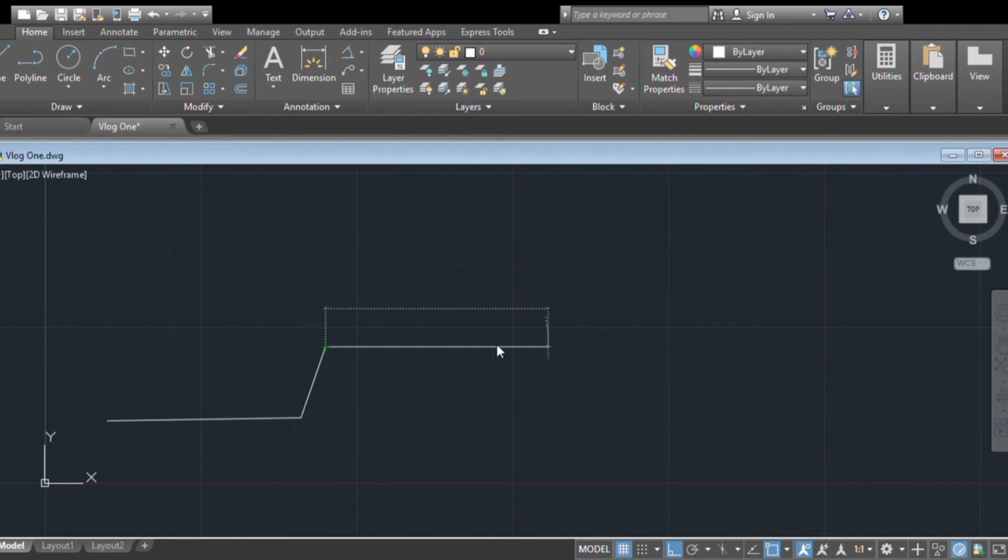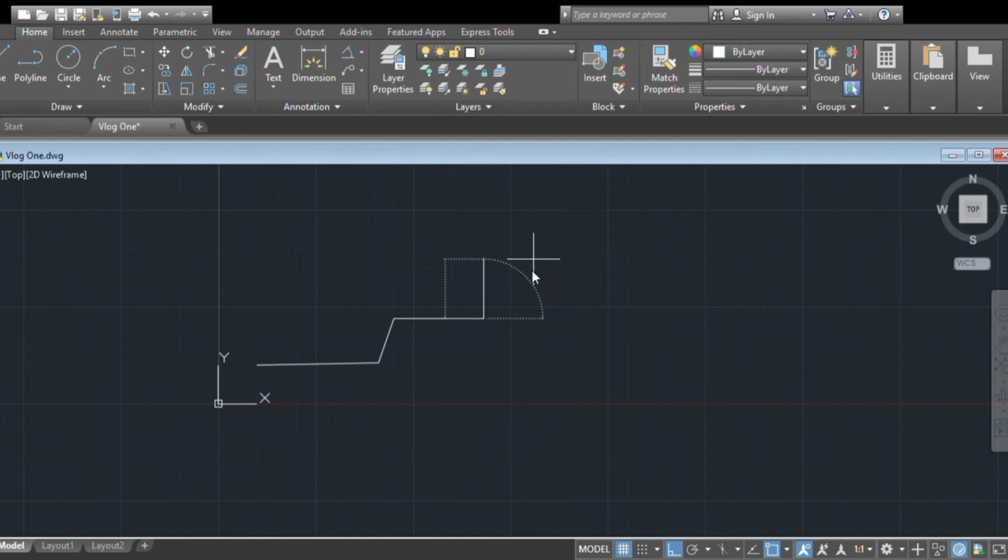After this, we will proceed to the next line, and we just have to make sure that we are following the coordinates and the lengths for us to complete this figure. So I have to put 1.4 tab 30 since we have to make sure that we have the measurement accuracy. For the next line, we just have to hold the mouse vertically and simply type 2.1 and enter. As you can see, we already have the lower part of the figure.